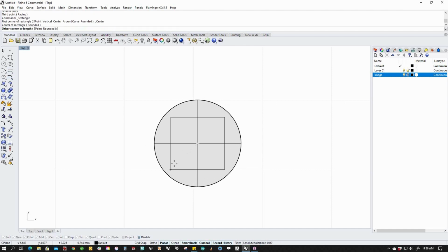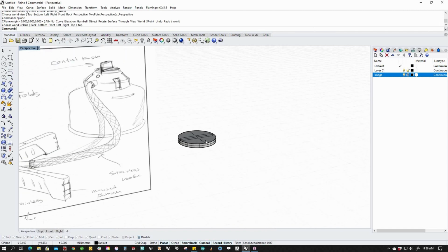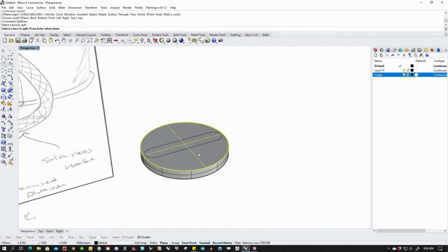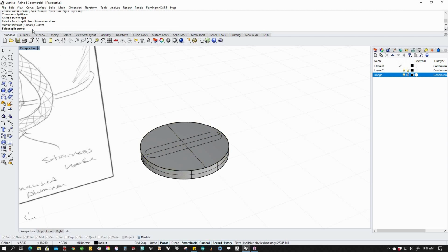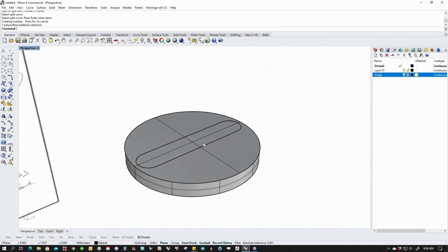And the reason I didn't get a center originally is because I got rid of that radial shape and changed it to have the flat cap, and the flat cap is just a trim surface, so it doesn't have that radial center. All right, so that's the piece. And then I'm going to use a command called split face. This is the face I'm going to split. I'm going to use a curve, which is this, and it took the poly surface, but it just broke that face off. Now that's cool, but what can I do with it?